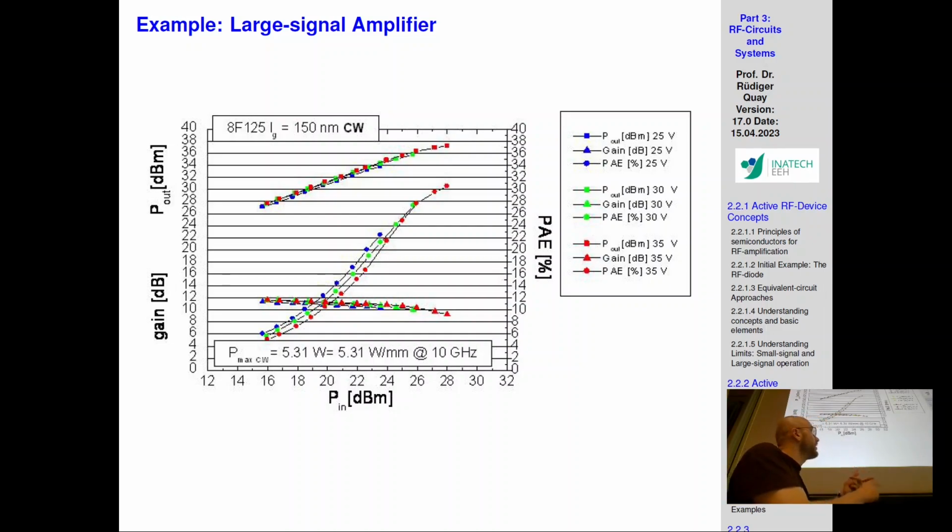It means a higher output power, and the gain curve is not in this flat area. It is not in the area where it is linear, but it's starting to enter compression. And then the entering of the compression point is usually something you measure. Okay, first being linear, and then I'm entering compression, and here is where you enter compression. You measure how much the difference is from your maximum point. Is it 1 dB? Is it 3 dB? Because this 1 dB or 3 dB here will be a reference to how much output power you have there. As high of an output power as possible, because you're designing a power device. You want power from this device, nothing else.